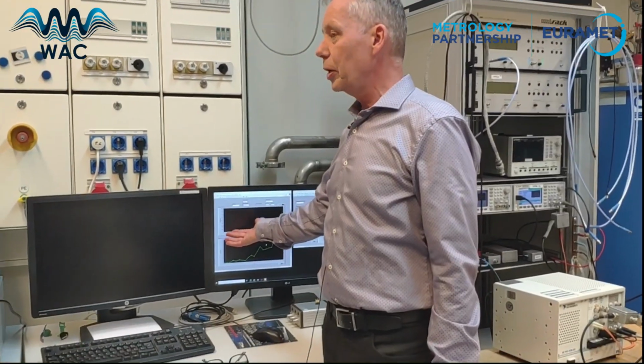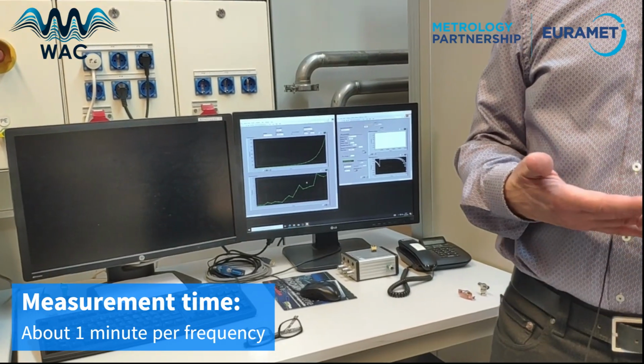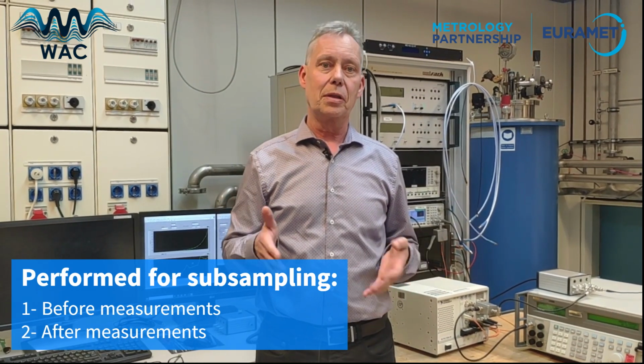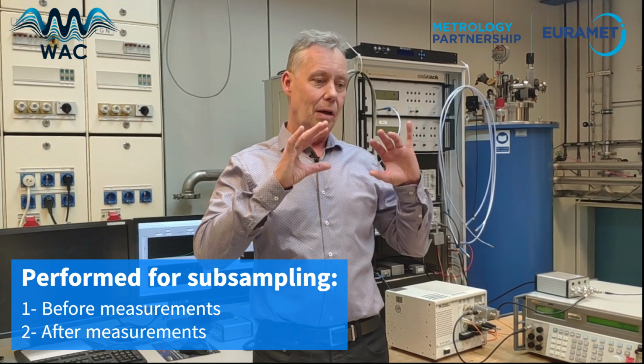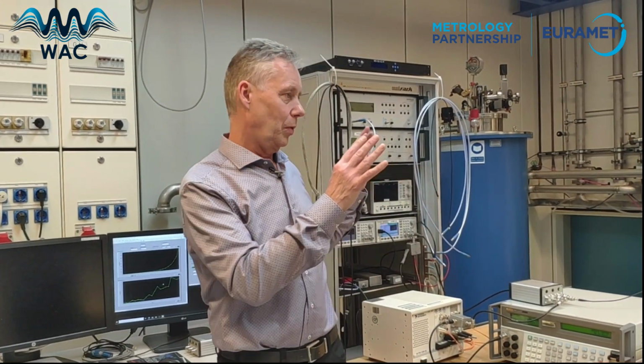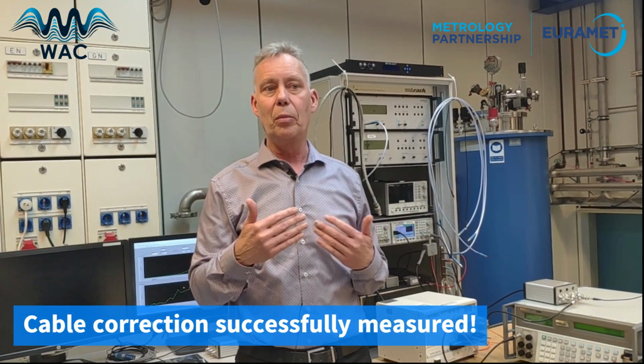Every frequency we put into this measurement routine takes about 1 minute. So for these 20 frequencies, it only takes 20 minutes, and usually we do this before doing subsampling measurements and afterwards, so that we have the data and the cable correction for the system as it is at that moment, with the same helium level and so on.